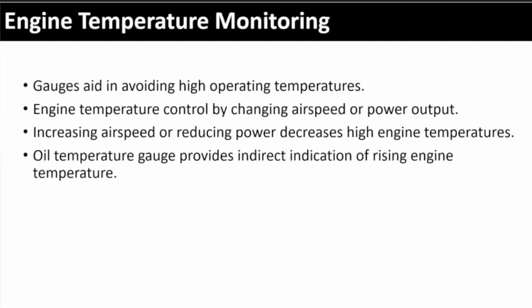All right, gauges to avoid high temperature. We already talked about the oil temperature gauges and oil pressure gauges. Monitor that stuff. Most airplanes are going to have some kind of cylinder head temperature gauges. Monitor that, right? We always tell everybody, you're flying VFR, where should you be looking? Look outside the airplane, right? And then you're scanning your instruments, spending a couple of seconds, look at everything, develop that good scan. Make sure you're where you need to be on airspeed, on power setting, look at your fuel gauges, look at your pressure gauges, right? Always keep monitoring those gauges.